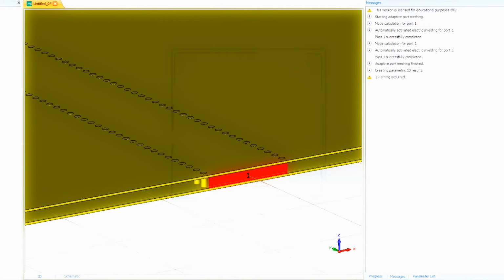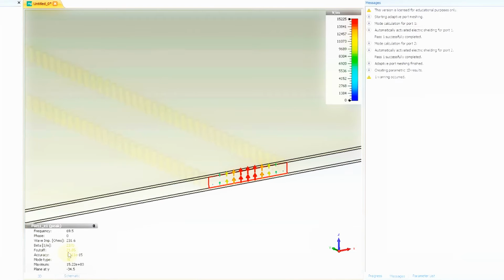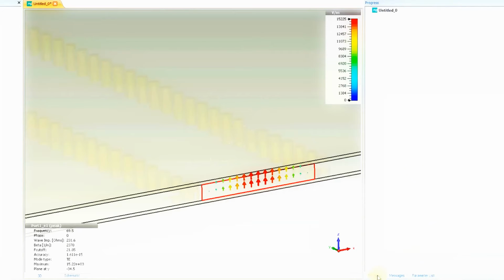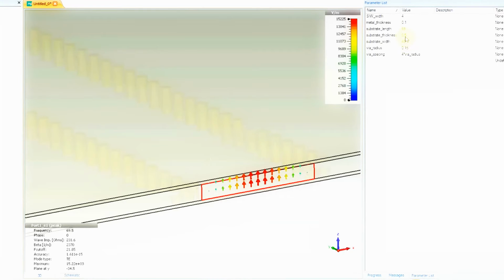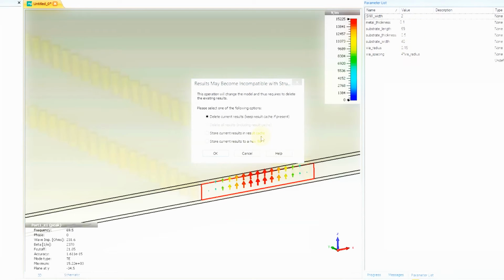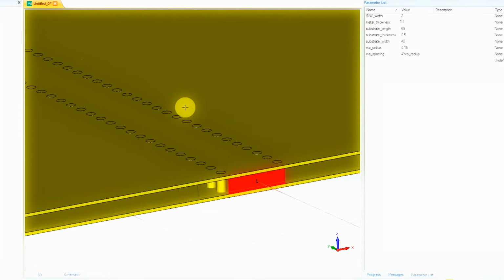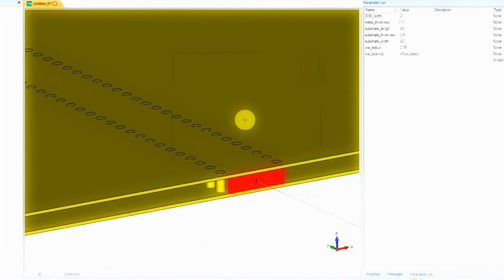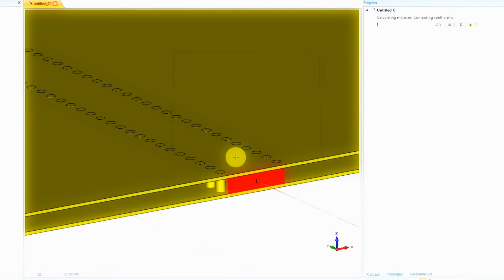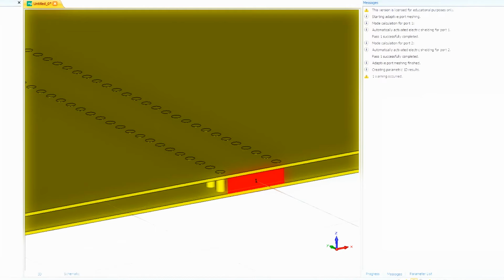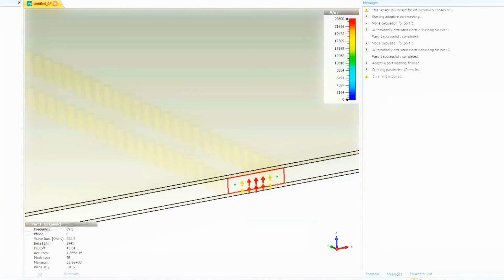As I said, if you'd used your analytical equations like good Boy Scouts, then this wouldn't be too much of a problem. Okay, now we're getting a little bit closer, 21 gigahertz. Looks as though this SIW is going to be very, very narrow for these high frequencies. SIW width 2 millimeters. Try again. Okay, now it's looking very narrow. Okay, it's finished again. Port modes, port 1, E1, F cutoff 43. Okay, so now we're in the sort of right order of magnitude here.